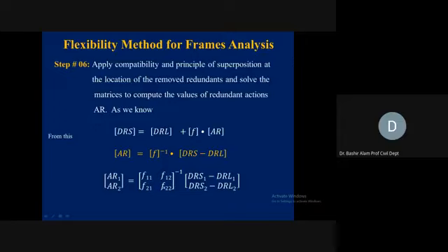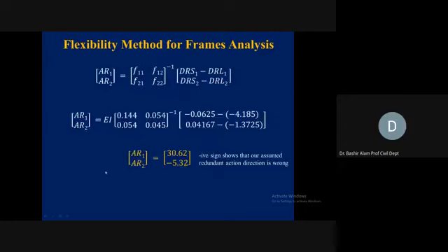Why do we see this flexibility coefficient 2 cross 2? Because the structure was statically indeterminate to 2 degrees. We plug in the values by putting the values here. Now, why was it 1 over EI? Why is it becoming EI? Because we took the inverse of this one. So instead of 1 over EI, it became EI.